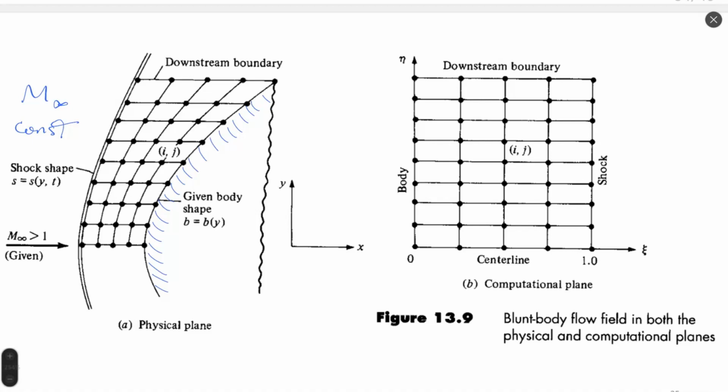This is why, since in many applications we would like to optimize computational time and complexity, we would like to know this shock wave. The shape of shock waves, as I told you, can be defined by empirical methods or complex analytical methods, for example, published by NASA. But the shape of this shock wave can also be calculated approximately by a preliminary numerical simulation.